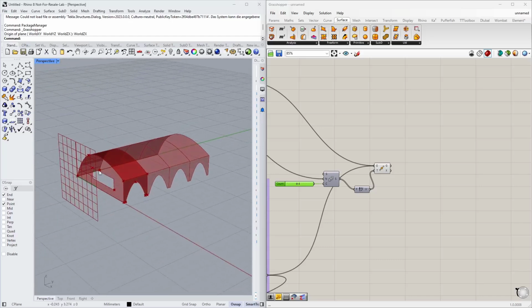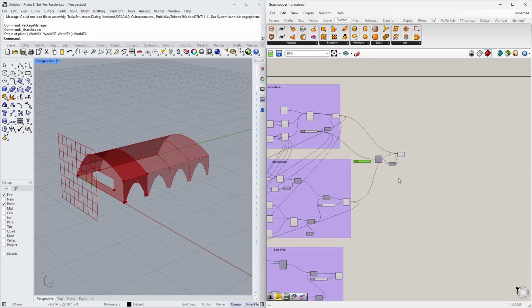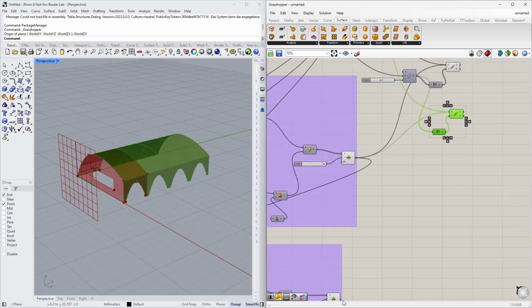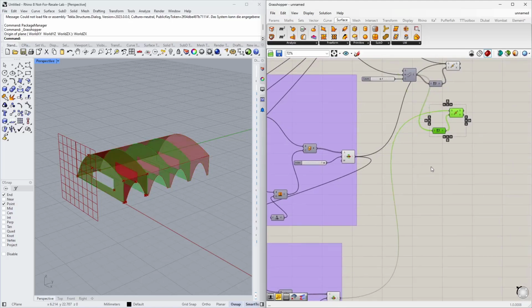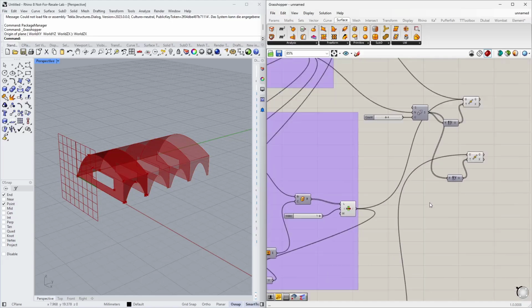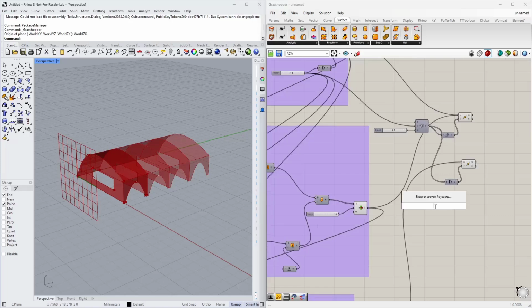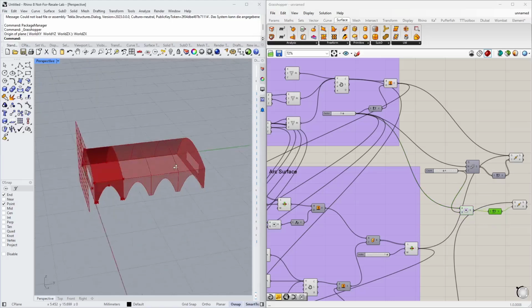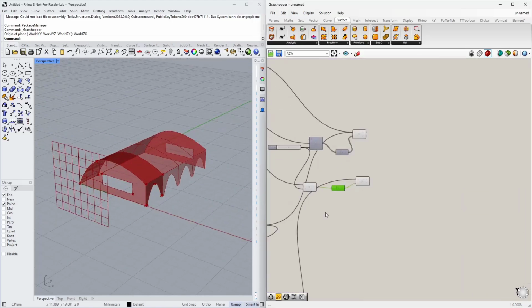Now I only have to copy the front surface to the end. So I use another move command for that. And I copy this surface. Of course, not multiple times. I only want to have it one time. And then the distance for this is actually a little multiplication. We simply multiply the extrusion length with the amount of copies. And that's the length that we need to copy it from the front to the end. Okay. So far so good.